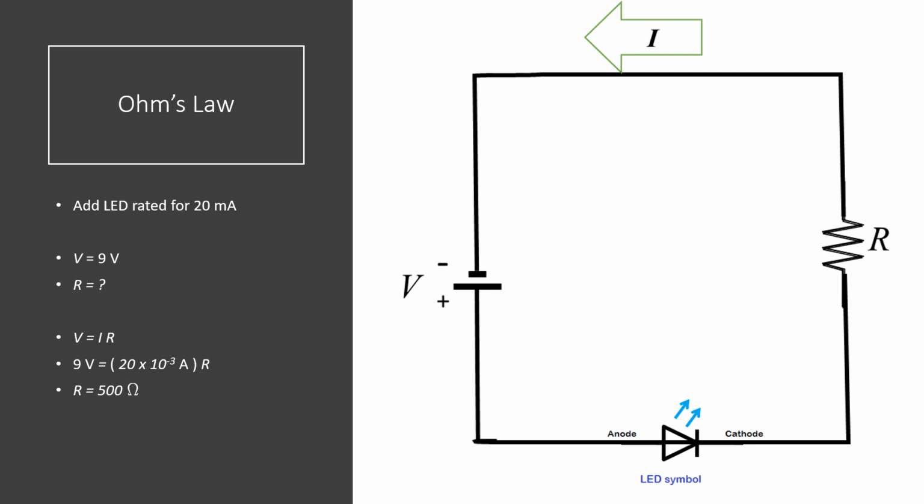So what we do is we're going to put a resistor into our circuit, and we can actually calculate the size of the resistor that we might end up needing using Ohm's law, and we get one that might be rated at, say, 500 ohms. That would essentially reduce the current to a level that we could insert this LED without blowing it out.